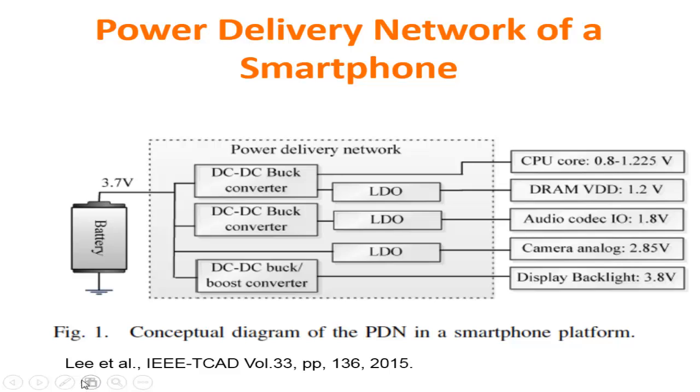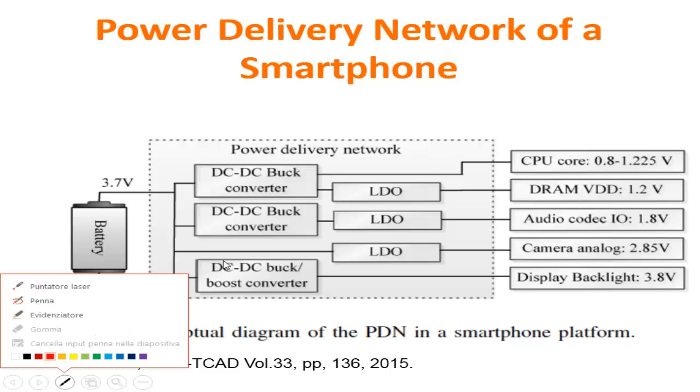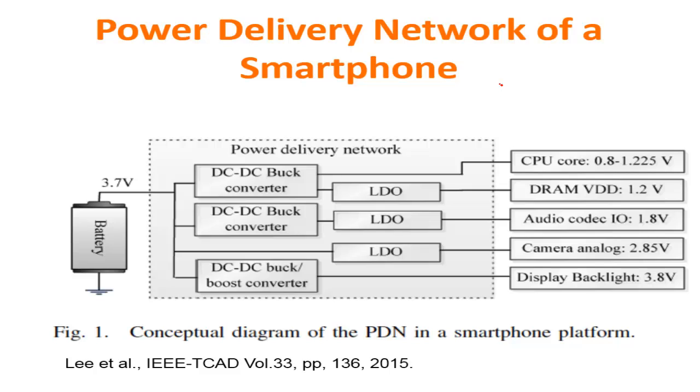Let me write this: the dynamic power, which is the single most important component, is 1/2 the total capacitance of the chip times the supply voltage squared times the clock frequency times the activity factor, which is on average the percentage of gates that switch at any given clock period.